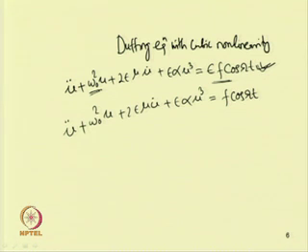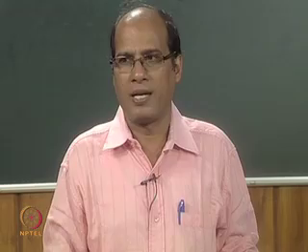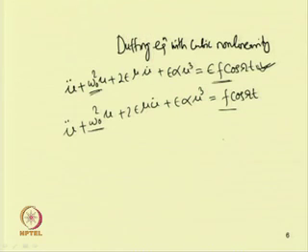But in the second case, as the forcing term f cos omega t is of the same order as the linear term omega 0 square u, last class we have seen two more types of resonance conditions: the superharmonic resonance condition, and the subharmonic resonance condition.